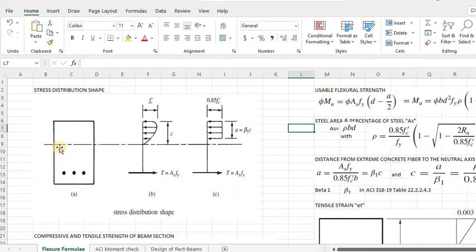So basically anything below the neutral axis in the concrete doesn't really do anything. It's only the steel that counters the tensile forces, right? But anything above the neutral axis is taking on the internal compression, right? So that's why in this representation here, you have the tensile force only held by the steel. Although the concrete will hold the steel in place and bond with the steel to make all that happen, it doesn't really do any tensile countering.